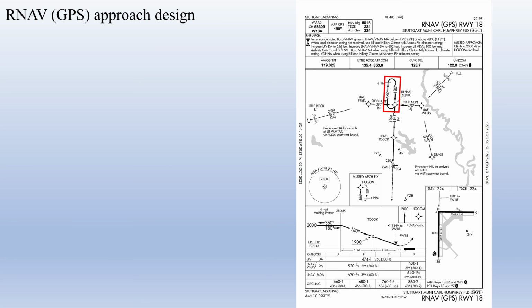These approaches do typically include a holding pattern in lieu of a procedure turn at the intermediate approach fix should a pilot wish to utilize it. This makes this fix double as an initial approach fix when you pass over it the first time on your procedure turn outbound, and an intermediate approach fix when you pass over it the second time on your way to the runway, which is why it's labeled IF/IAF.